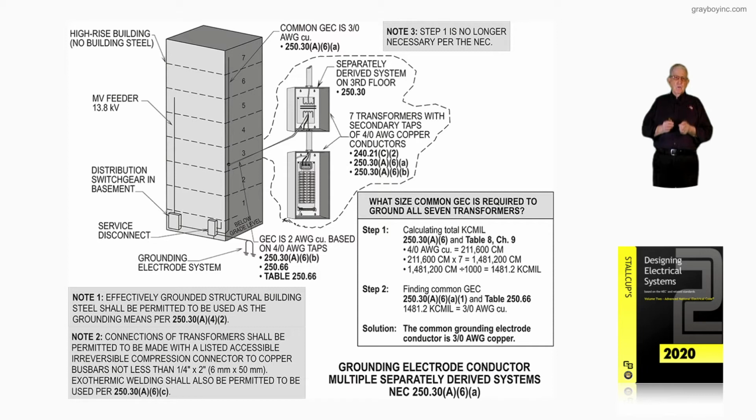Then they suggest going to the bus bar. And notice that's the minimum bus bar that you could use, or maybe even a larger one. And you'd say, well, why would I want to do that? That would be like that transformer you see in the illustration. It could be a K-rated isolation type transformer with a tap from the secondary to the panel board.